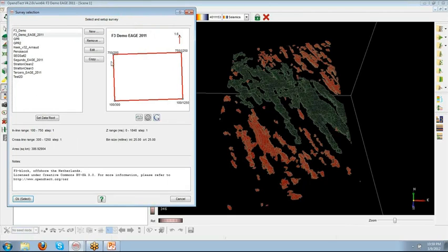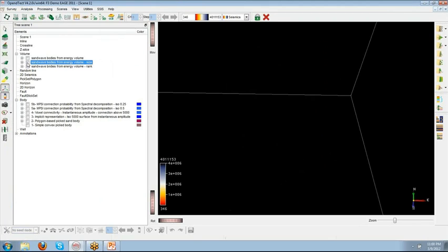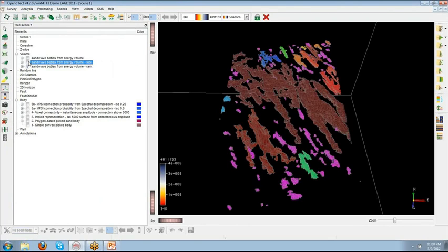And if you multiply this number by the bin size, so 25 meters by 25 meters, and by the sampling rate that you have to convert to meters, so 1, then you can get an estimate of this volume, of the used volume in cubic meters in this example. So this is how to use the Voxel connectivity filter.